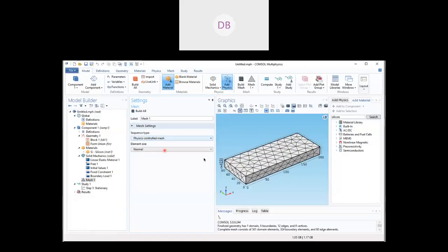The difficulty with this software, or any FEM software, FEM being finite element modeling, is that as the size of the device reduces, if any one dimension is reducing, there arises a convergence issue. Here we have taken only some 20 micrometer thickness. Imagine it is 20 nanometer.